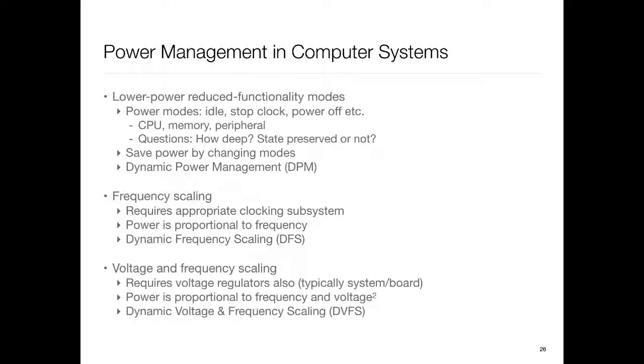What this leads to is the following. I can lower the voltage and lower the frequency. If I need a lower speed, my best win is to lower both of them accordingly: lower the frequency and then adjust the voltage so that I can sustain that frequency, but nothing excessive. This is called DVFS, dynamic voltage frequency scaling, and this gives you energy gains also.